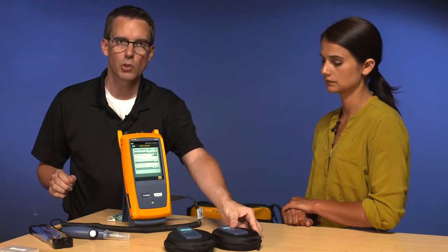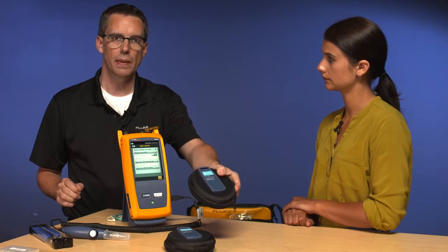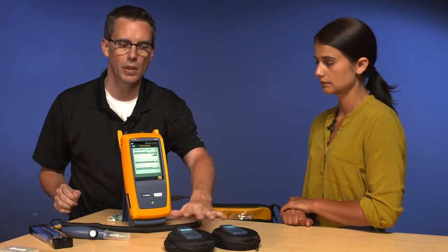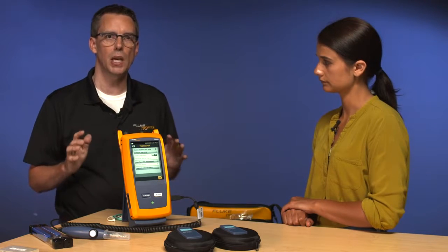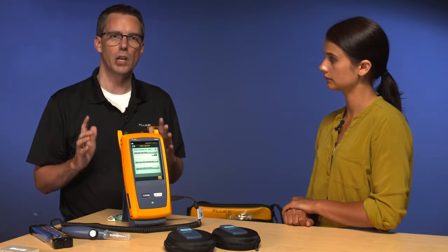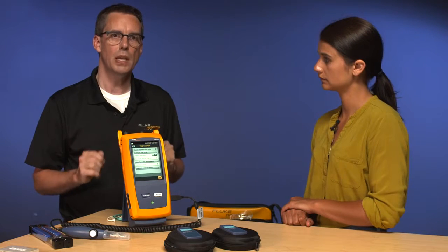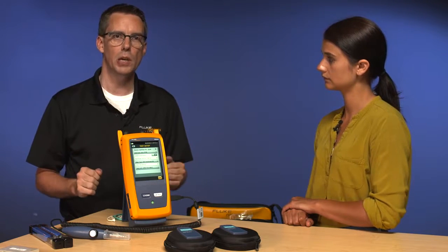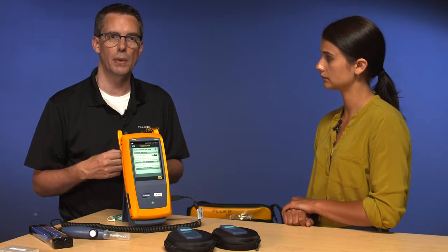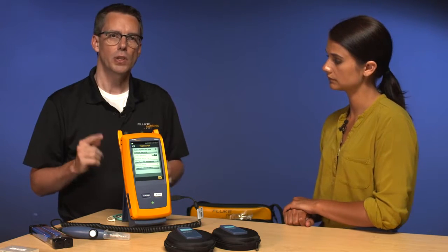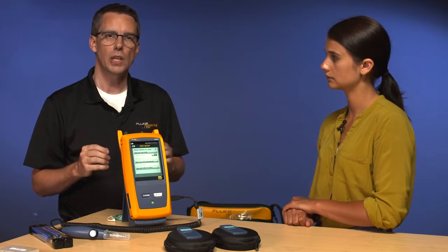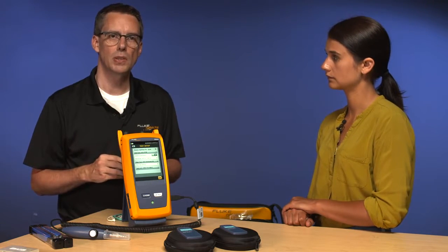Now you'll see that I've got two fibers on the table here. This other one I'm going to call my tail fiber. It's the same as this one, but I'm going to call it my tail fiber because a lot of folks today are still just using a launch fiber only. You should be making an OTDR measurement with a tail fiber as well. And when we come on to do launch compensation, I'll talk a little bit more about that. I'm going to leave it off, and the reason why I'm going to leave it off is when you do the launch compensation, it will turn this on automatically for you.